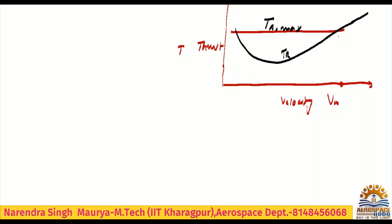It will be going like this. This is the velocity, the free stream velocity. Available thrust and required thrust will cut at two places. Because this axis is velocity, at the origin the velocity is 0. Whatever velocity you get at the first intersection will be the minimum, and at the second, the maximum. That's the reason I first explain the meaning of maximum velocity: wherever the available thrust and required thrust curves cut each other.